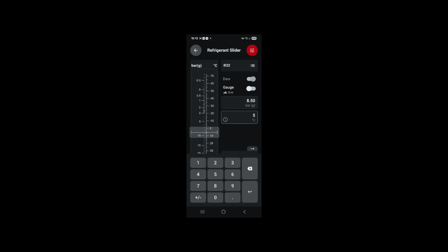If you want to pressure test the pipes and all these things, normally you would test to the condenser pressure. In the condenser, let's say you are operating at 35 degrees Celsius, you are at 20.89 bar.